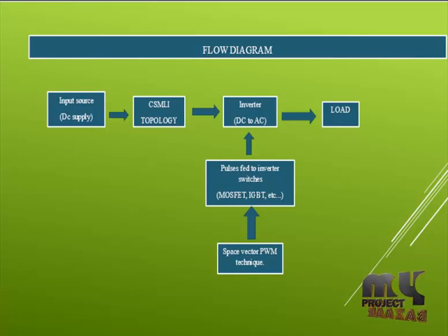In this proposed work, we overcome the drawbacks of the existing system and compare the result with the existing method. The proposed circuit is named the basic unit and contains two DC power supplies, two capacitors, two passive power diodes, four active power switches, and six MOSFET switches. Input source may be photovoltaic cells, batteries, or fuel cells can be used as a power supply in this structure. Switches SA and SB are used in series parallel conversion respectively.